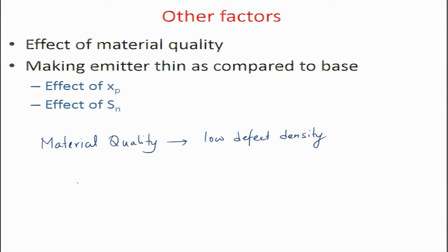So if you look at this IV curve, okay, the idea is to get an IV curve which is like this, but if your IV curve happens to be like this, alright, something like that, this means your I_V is more dominant than it should be. And remember, I_V is made up of what? I_V is made up of your diffusion current, space charge current, and radiative recombination current.